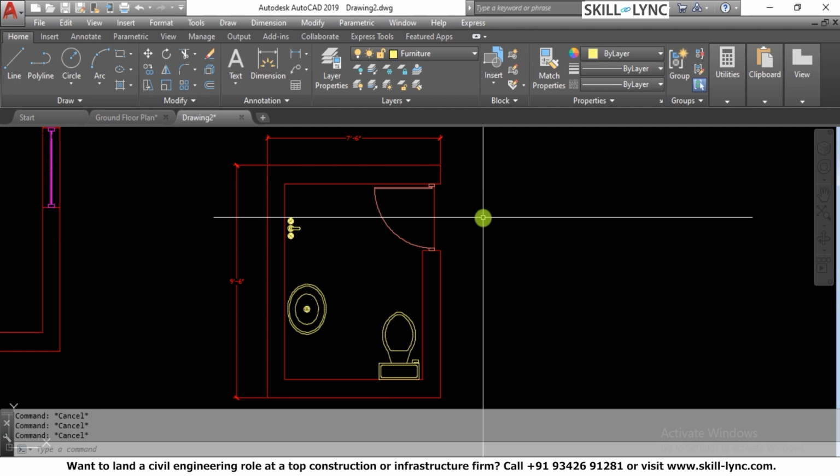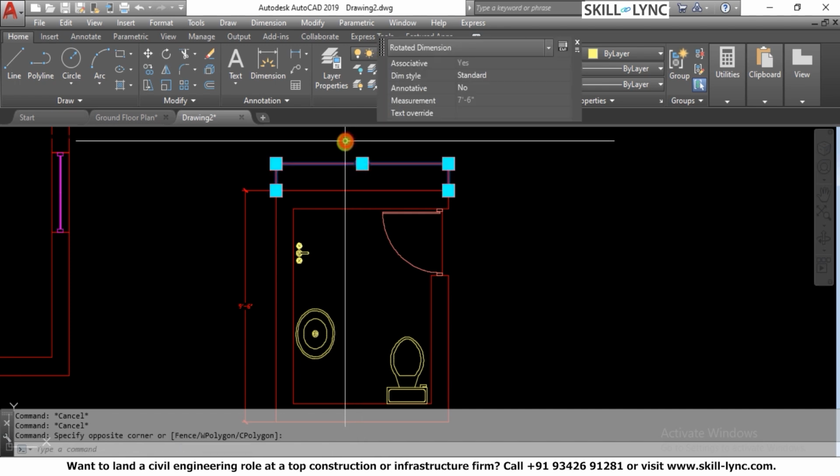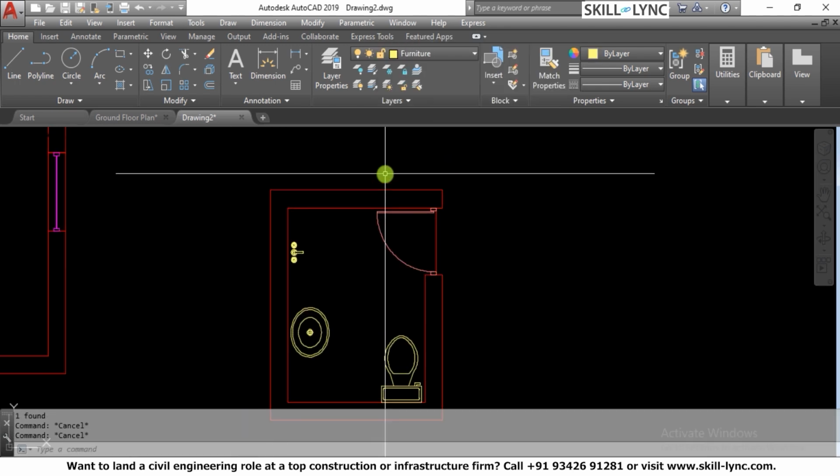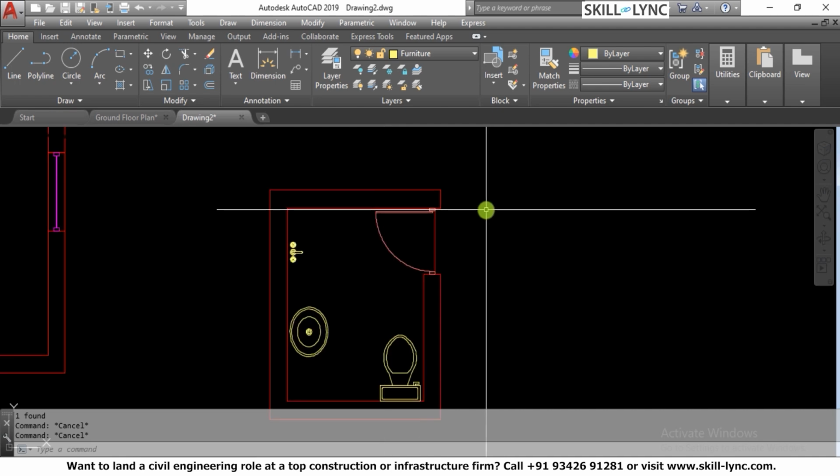So placing the objects with the block. You can block entities and different kinds of block objects into the drawing and make it more descriptive if you want. Right, I basically want to finish this particular option here, then we will be going with measure and divide, and we'll be doing rebarring kind of thing. So how we can place rebars at equal intervals using the blocks and the shapes of the rebars, so that we can understand how it can be used in our structural drawing also.